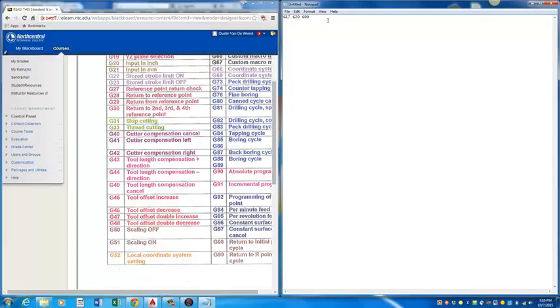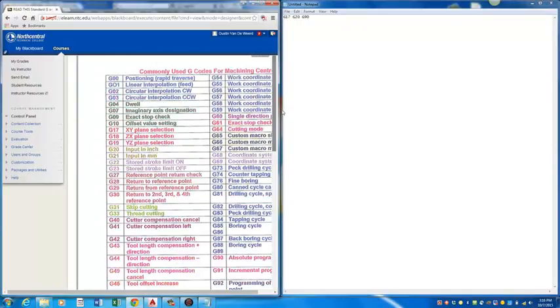So in my previous video we talked about the X and Y planes. We didn't say much about the Z. Z is actually the vertical axis, or raising the pen up and down on our CNC trainers that we have in the lab. So my first move here is going to be the safest move on the machine, which is to bring the spindle or the pen up.